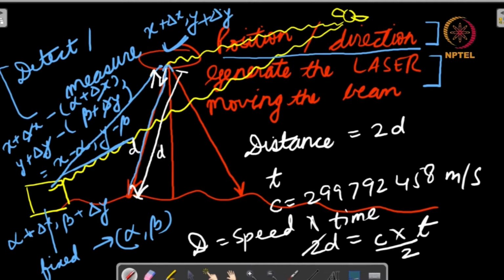So we know very well the distance d from the object. Now if you know the position of the aircraft and you know this distance d, and you exactly know the direction in which the laser was shot, you can compute the coordinates of this particular point. Similarly, when you scan the area, you can compute the coordinates of this point, of this point, of this point, of this point, and so on. And by joining these points together, we can generate a digital terrain model of this area.